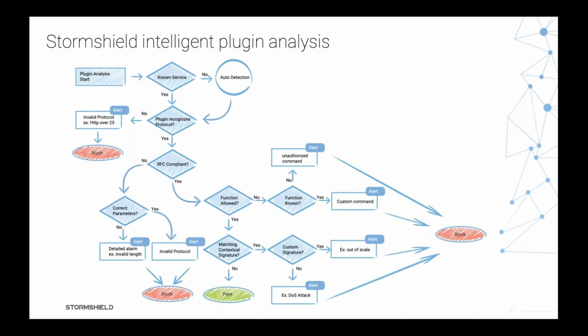And following that, it will check the internal details of this protocol. If it's HTTP, it will check whether the HTTP command is allowed or not. If it's Modbus, it will check whether the function code is allowed or not. Whatever type of protocol, it will check. The good thing about that is that only when it's matching everything, it will pass. Other than that, it will not only be blocked, but you will get a detailed message including why it was not matching and why it has been blocked, with the detailed information that is required.